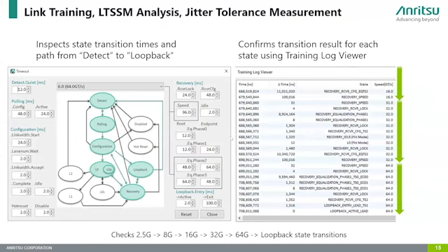This is an example of the LTSSM through generation 1 to generation 6. You can see what's going on with the training sequence. Then the BERT has a function to analyze each step of link training, and you can manipulate the timeout seconds from the table.